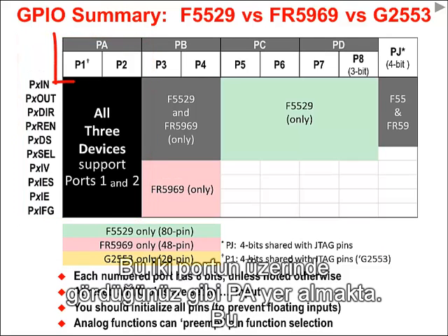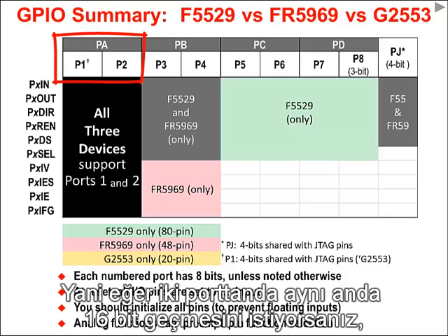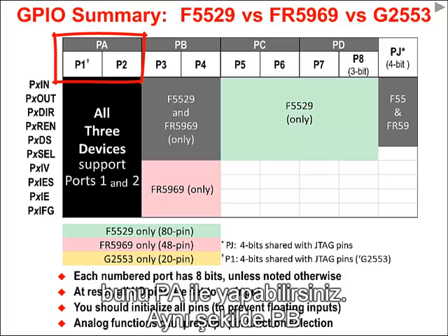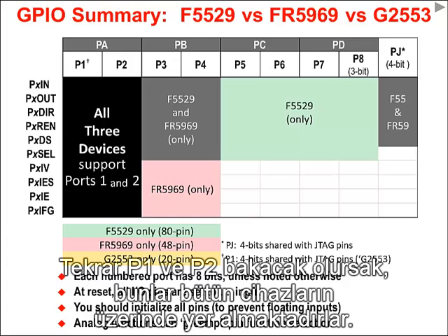And you can see up above there, port A, that's actually a way we can talk to 2 different GPIO ports at the same time. So if you want to do a 16-bit write across both ports simultaneously, you'd address that with PA. Similarly, PB, PC, and PD. But let's go back to ports 1 and 2. These are available on all the devices.